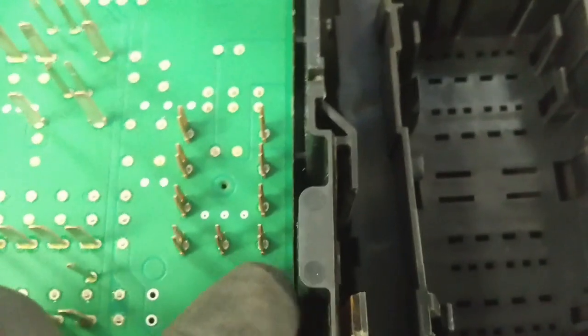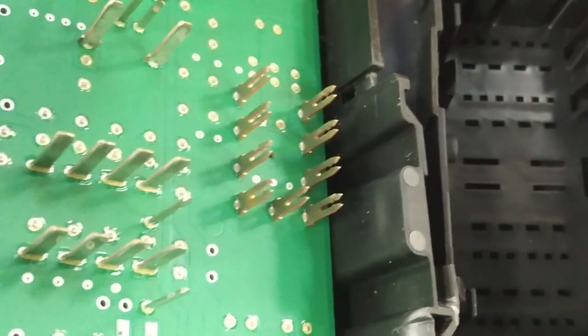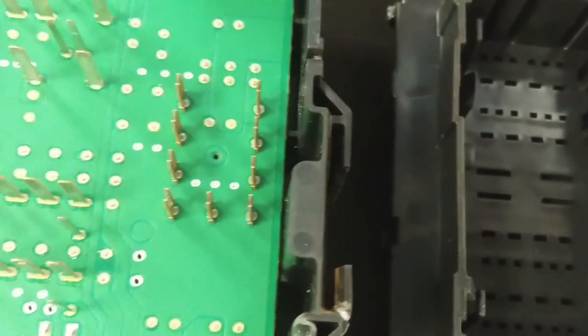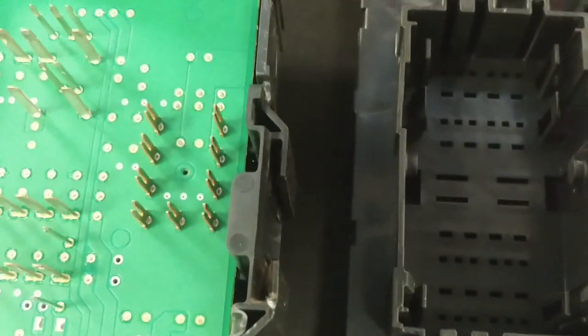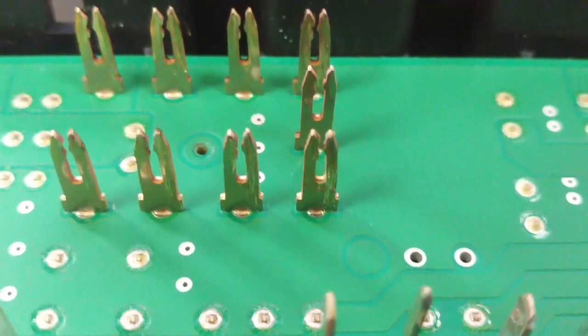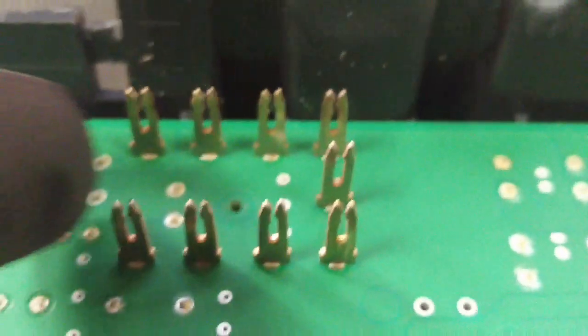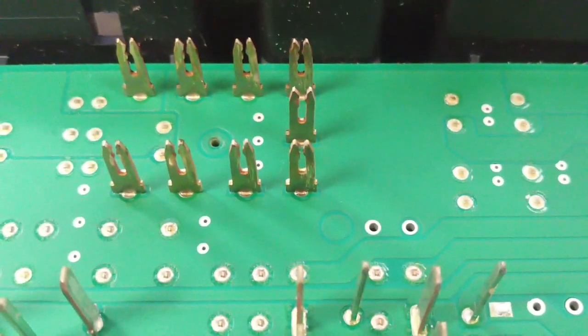So got the back off, and looking inside here, these are the 3 pins at the bottom that showed oxidation on the outside of the panel, but the inside of the panel looks pretty darn clean. We're going to crimp those pins just to make them a little tighter and clean them up with a diamond file, and put some dielectric grease and put a new relay in there. So I've cleaned up all those with the diamond file, and I've re-crimped them with a pair of needle nose. I'll maybe do this one up here in the top corner one more time. And we're going to put it all back together again with a new relay.